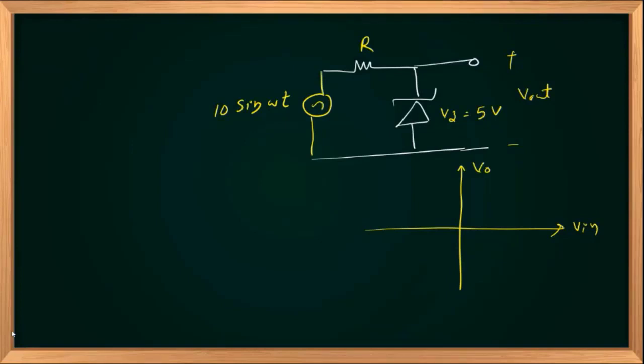As we discussed, we have 3 different cases for our Zener diode, and we don't know which mode it is operating in. So we will open it. Its anode was connected to the 0 volts reference, and cathode was connected to this output node. When the diode is open, the right side branch is open and the downward branch is also open.